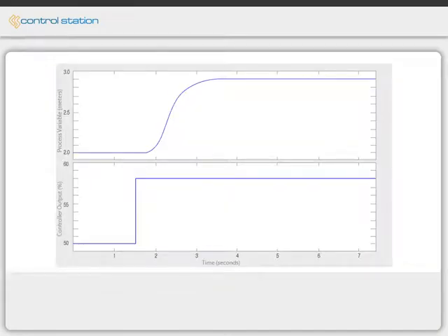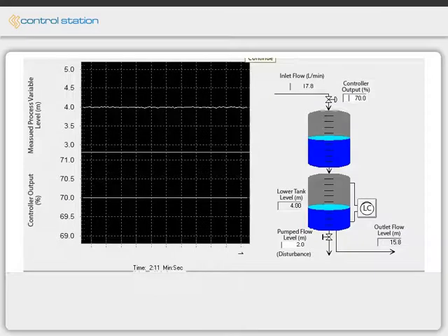To learn about dynamic behavior, we analyze measured process variable test data. One way to obtain this information is by performing a step test. A step test is generated by suddenly changing the controller output signal and seeing how the process variable changes. To fully illustrate the concept of performing a step test, an example is shown on your screen.